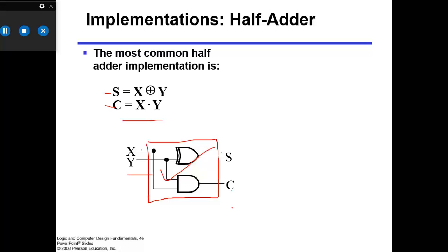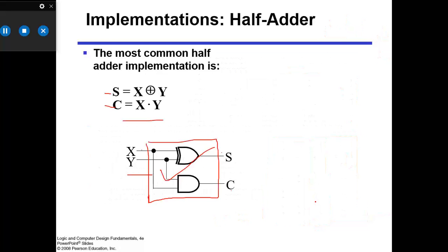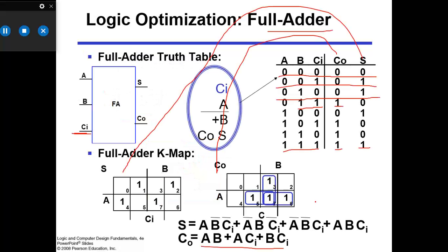The most common adder, the half adder, is implemented in this way. From this equation, we can see that the sum follows the pattern of an XOR gate and the carry follows a simple AND gate. So we can implement this by using an XOR gate and an AND gate and get a half adder circuit for basic addition if our inputs are 2 bits.